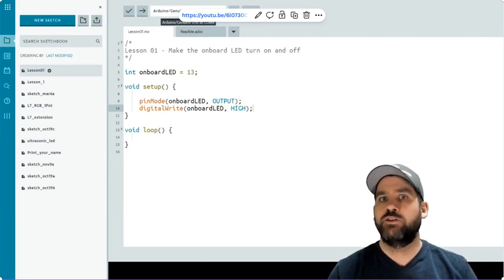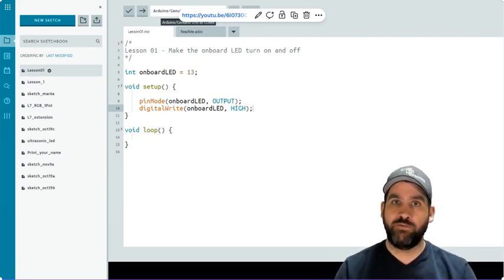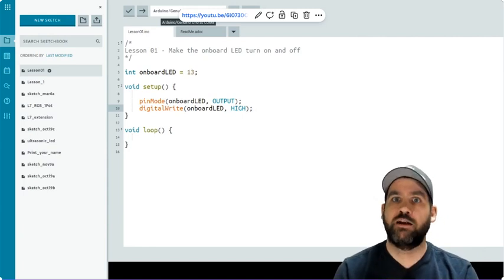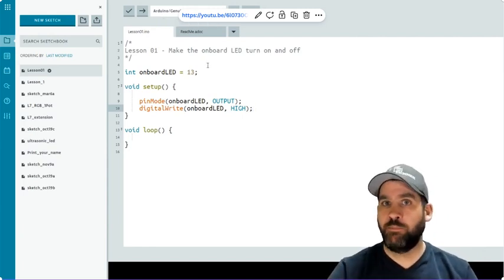So have a look. My Arduino is plugged in, and you'll now see that it says Arduino Genuino Uno at COM8. So assuming you did good in the getting started guide and you got everything configured properly, you have the right drivers running on your computer, when you plug that Arduino in, that should change for you. So at this point, we are ready to upload our code.